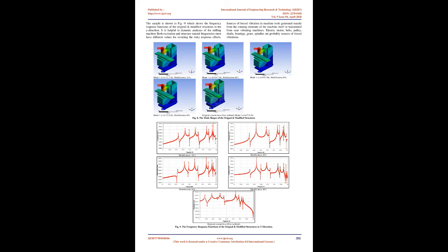Modal analysis is carried out on the milling machine column. When exposed to loads or displacements, all real physical structures act dynamically. The equations of motion can be written depending on solving the eigenvalue problem equation of multi-degree of freedom systems as follows, where U denotes the eigenvectors, M is the mass matrix, C denotes the damping matrix, K is the stiffness matrix and F(t) is the applied force.